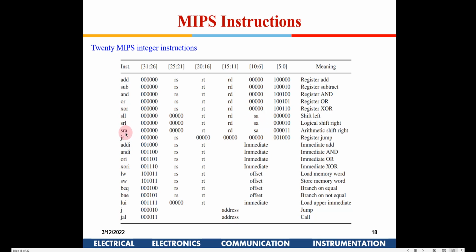Now for shift L and for these 3, this data is going to change, right? Similarly, you have all these different ones. Here we said it is 16-bit data, for add immediate. From 0 to 15, from here to here, immediate means these are all 16-bit data. So this will be the add immediate, and the first few bits will be like this. This will be the source register, this will be the target register, and then the 16-bit data. So the total will again be 32-bit, right?